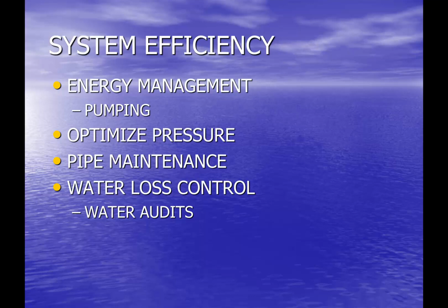So you typically have meters at the entry points, the source of supply, pump stations, wells, whatever they might be, and then are looking at, can we account for all that water? If we brought 10,000 acre feet into the system, did we sell 10,000 acre feet? And to the extent that we didn't, then where did that lost water go? Lost, or what we might say unaccounted for water. Because there are in reality real losses where we've literally lost water, whether it be leaks or something else.